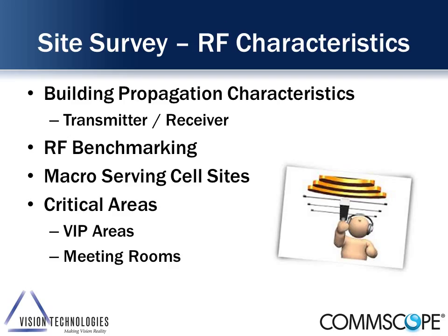And so now what you have is an issue called pilot pollution, where your cell phone inside the building sees so many cell towers, it gets confused as to what cell tower it can talk to. So if you've ever had a situation where you've got 4 or 5 bars on your cell phone but unable to make a call, that's an indication of pilot pollution and having too many cell towers penetrating into the building.